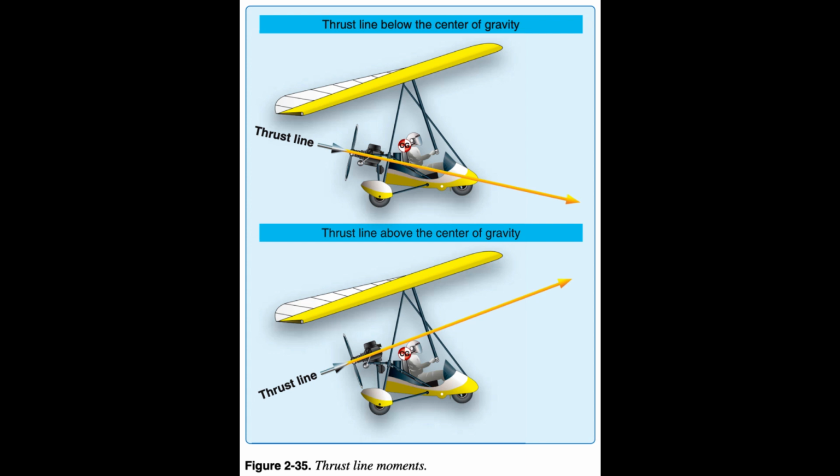With the thrust line above or below the CG producing these pitch and speed changes, they are usually minor for most popular designs. Larger thrust moments about the CG may require pilot input to minimize the pitch and speed effects. Most manufacturers strive to keep the thrust as close as possible to the vertical CG while also balancing the drag of the carriage and the wing for its speed range. This is why the carriage must be matched to the wing, so these characteristics provide a safe and easy to fly WSC aircraft.